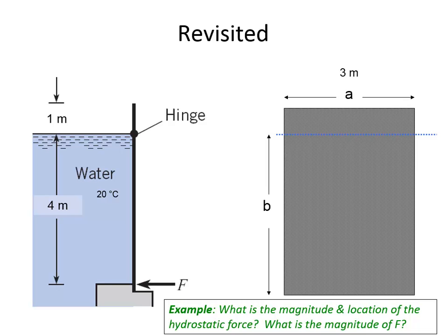Well, now that we've done that really specific example, let's work some of these more general examples that are in the slides. So, revisiting the idea of a gate where water's pushing against the gate, what's the magnitude and the location of the hydrostatic force? Now, we're not talking about F, the force required to hold it closed. We're talking about the hydrostatic force at first. What is the magnitude and the location of F?